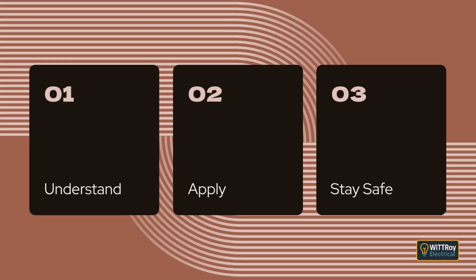Clause 2.3.6.2 Devices for shutting down. This clause details the requirements for the devices used for shutting down equipment during mechanical maintenance. The device must be manually operated, clearly show that it is in the off position, and be designed to prevent accidental closure caused by impact, vibration, or other disturbance. This ensures the equipment cannot restart unexpectedly while someone is working on it.